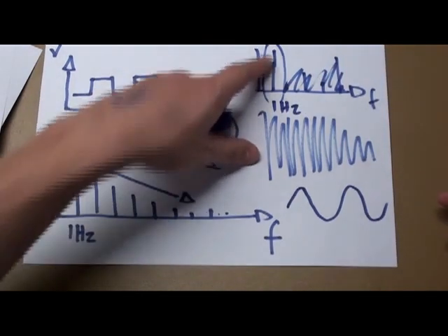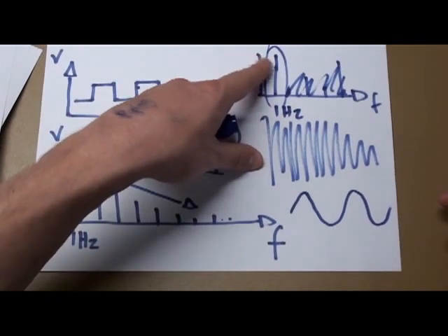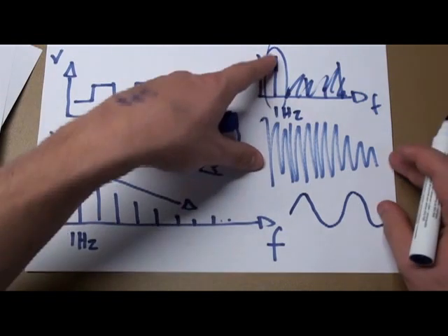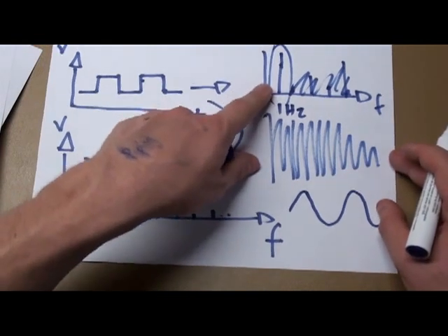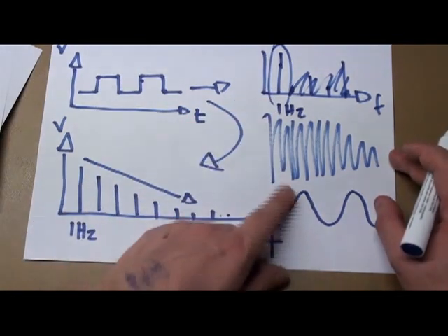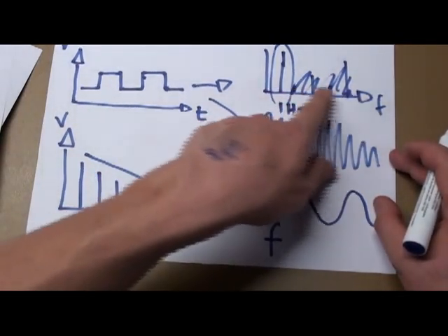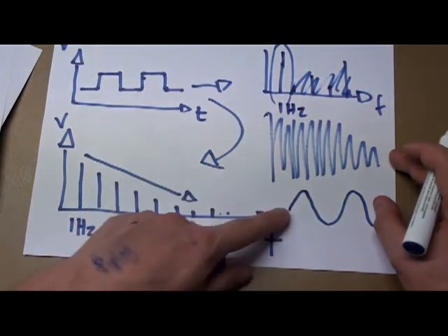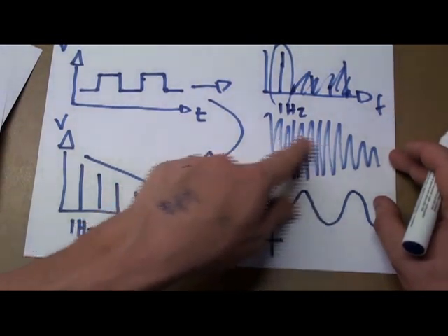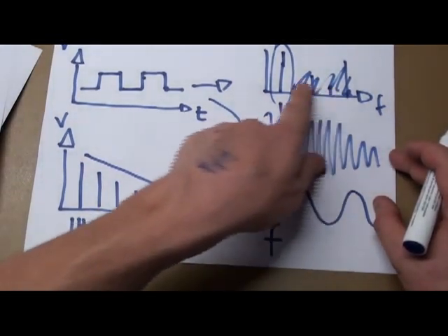If the signal we want is on the order of 1 Hertz, so it's not changing or cycling very fast, then we want a circuit that can delete this other stuff and turn this into the nice signal that we want. So we get rid of all the noise, or the frequencies that we don't want.